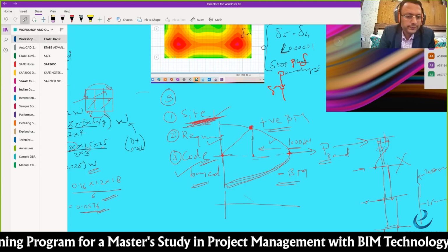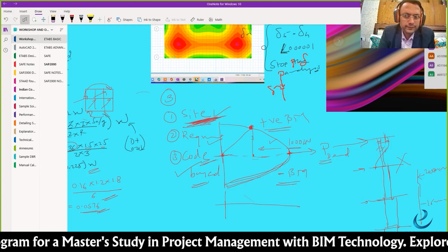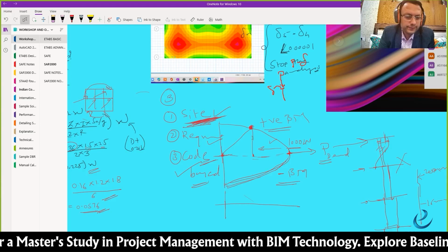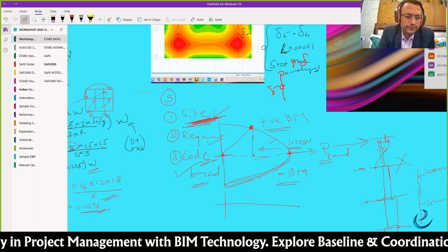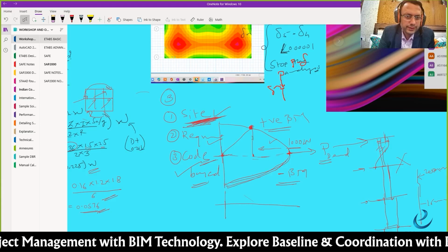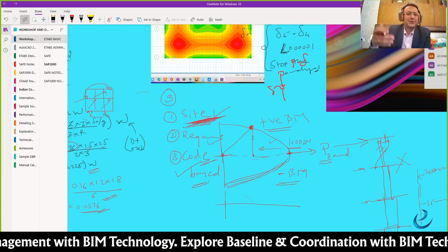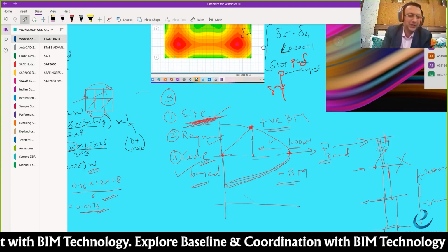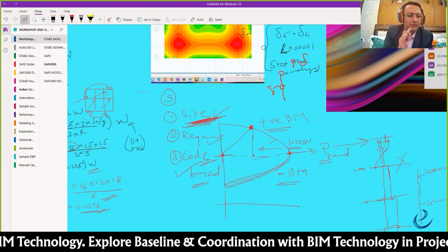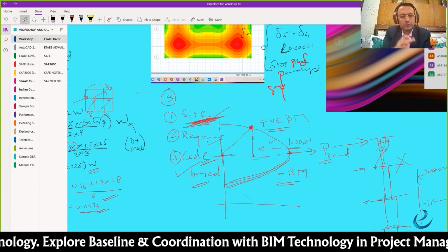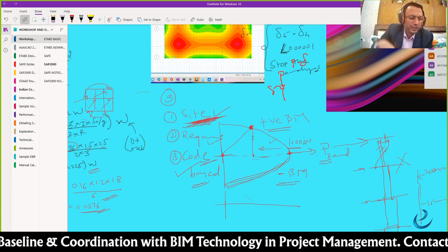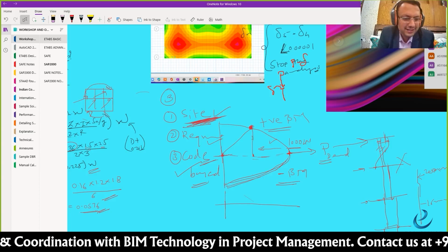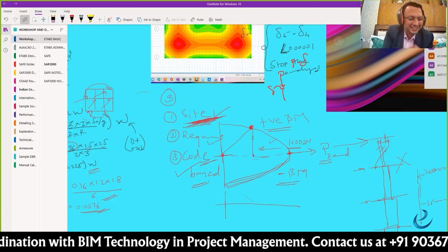You said that on a 16 mm bar, we can lap a 20 mm bar. Now, suppose my requirement at the top is a 25 mm bar. Can I start lapping this bar one floor below? So only one floor below you need to change the bar diameter from 16 mm to 20 mm, and on 20 you can go for 25 mm. That is the practical application.